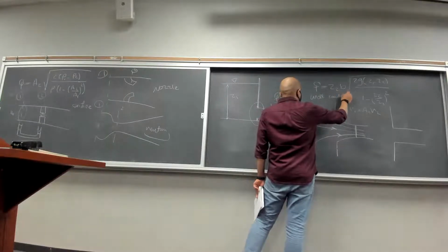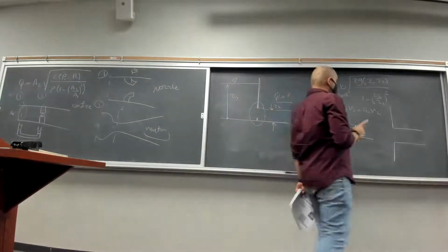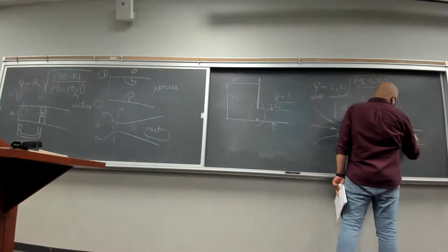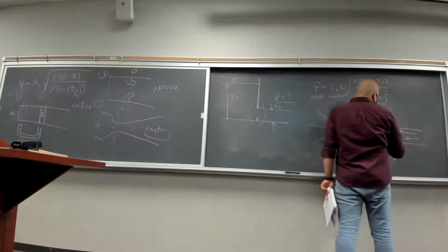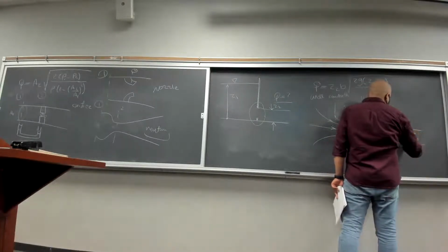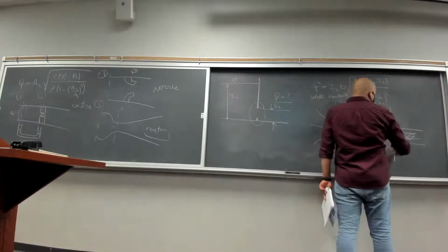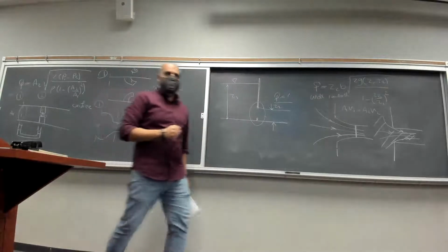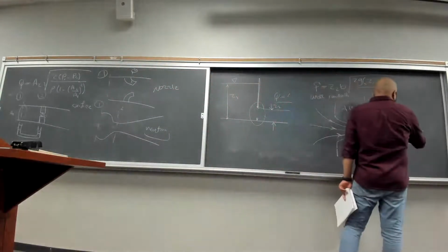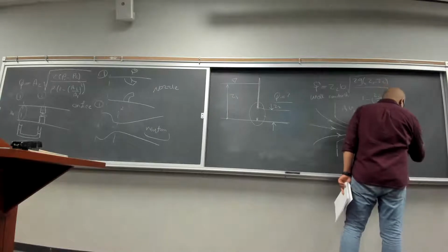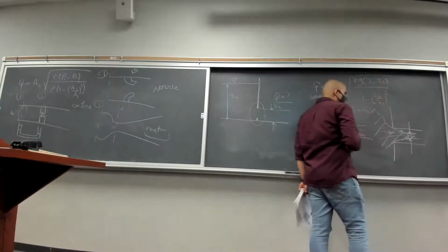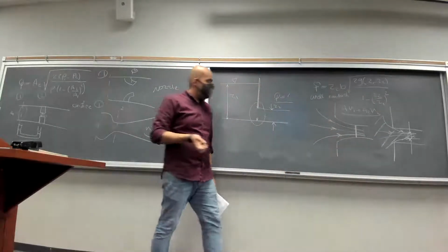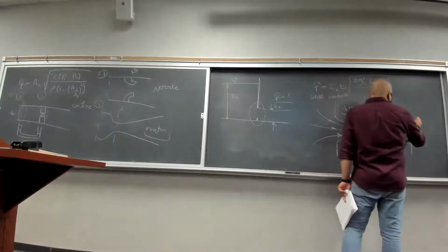But in a squared-off entrance, you will definitely get some flow that is going to separate from the wall. So your fluid is going to cover an area which is smaller than the pipe area, right? If you have this area, the area that is covered by the fluid, the same equation applies. But we usually don't have that. What we usually have is the area of the pipe.